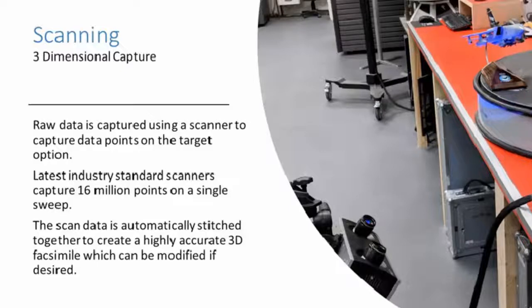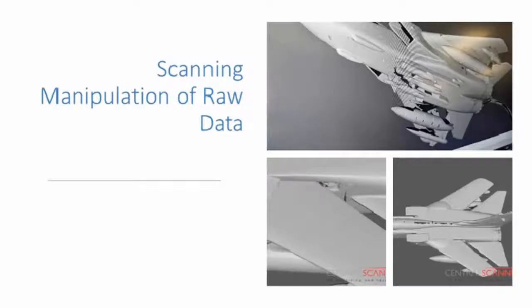The benefits of 3D scanning are already widely recognized within a range of industry sectors, including aerospace, automotive, and heavy industry. 3D scanning commonly aids reverse engineering, rapid prototyping, model making, as well as pattern and component making. The accuracy of the collected data means the scanners can additionally be used for QA purposes, including non-destructive testing and comparing physical dimensions of a component to its drawings. In our case study, you can see here, 3D scanning was used to provide a non-contact, accurate way of collecting dimensional data, which was then transferred to a standard 3D CAD package for additional modification prior to eventual ALM output.